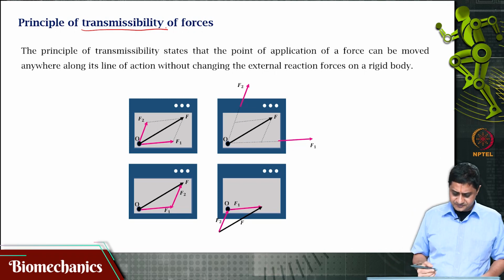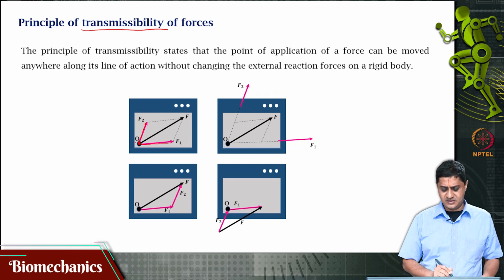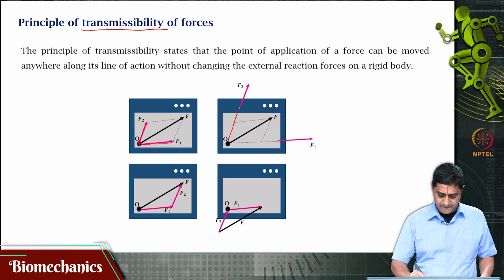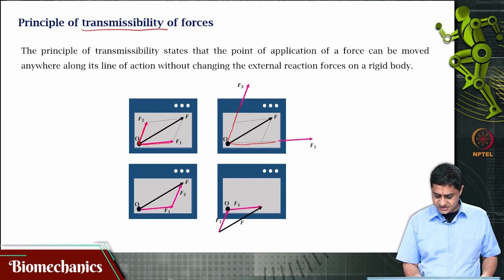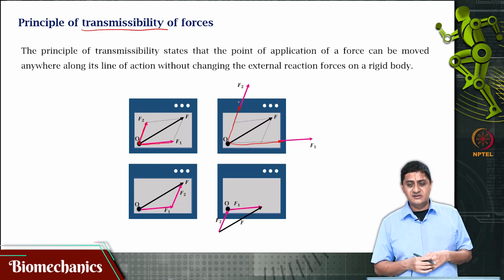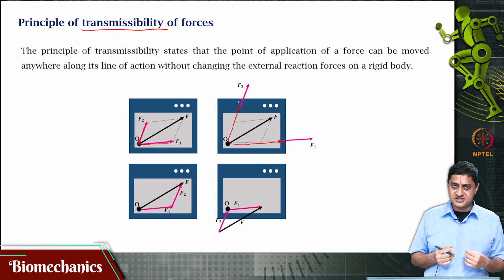That is, let us say in this case force F1 and force F2 are acting at this point O. Now I know that the line of action of force is along that line. The line of action of this force is along this line, right? Now I can move this F1 to act from this point and F2 to act from this point without changing the analysis. This principle is called the principle of transmissibility of forces.